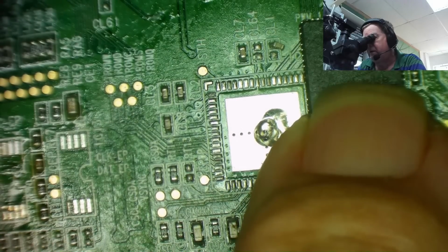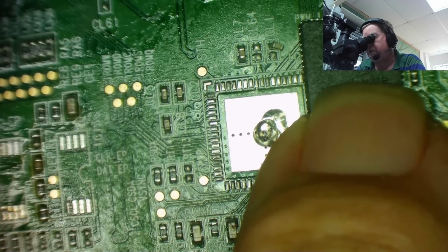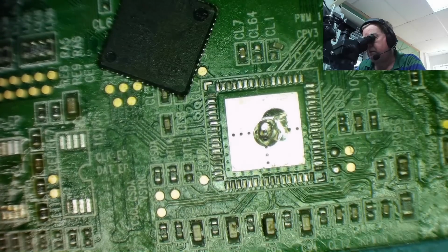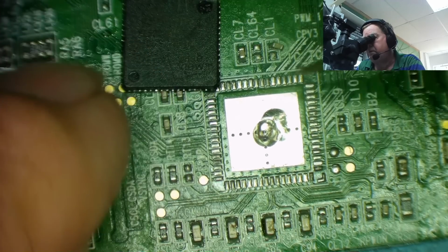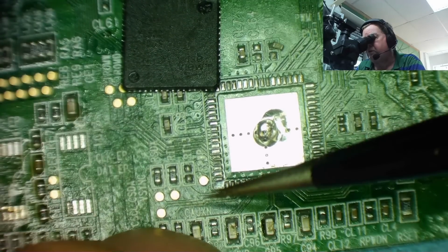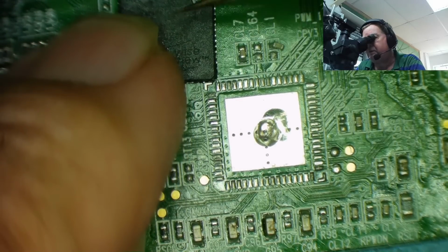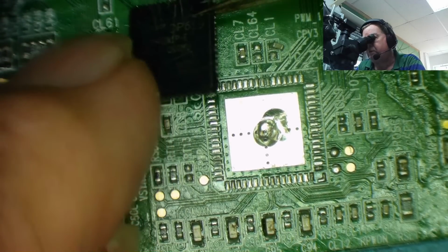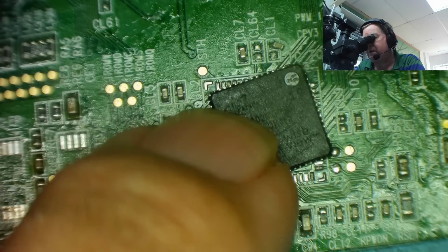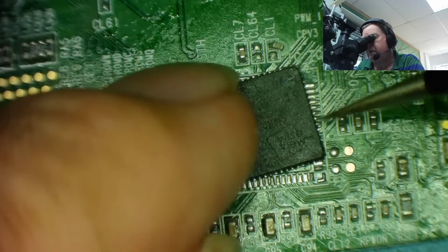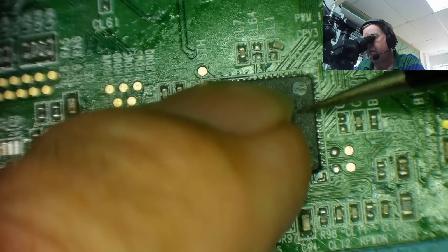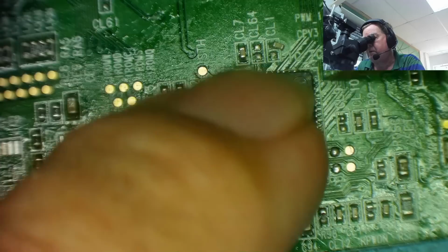We know the chips are that way round, as I made a note of it earlier. Oops. Strange, this one always has a cut off there, and oh yeah, there's a dot. There's a dot in one corner, and the dot is where that little cutout is. There's a little dot down there. Apart from this big one, there's a small one.